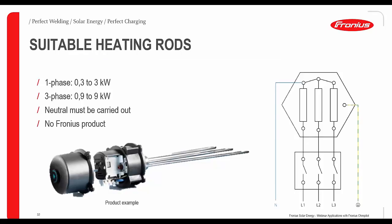A few words for suitable heating rods. What can be used there? The only thing you have to consider, please use only heating rods with a neutral conductor. This must be observed, otherwise we can't connect it to the Ohmpilot. The whole thing would be destroyed. So you have to use a heating rod with a neutral conductor, and it can be 1-phase or 3-phase, no problem. We also have no Fronius products, so no Fronius-branded heating rods or anything else.